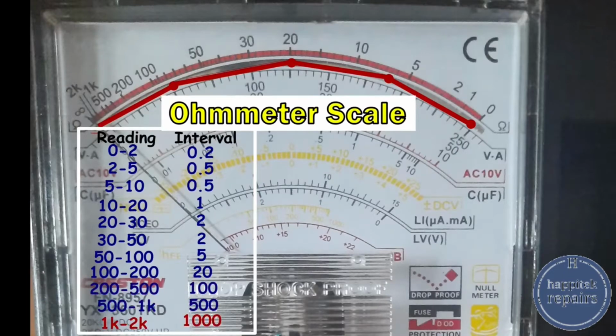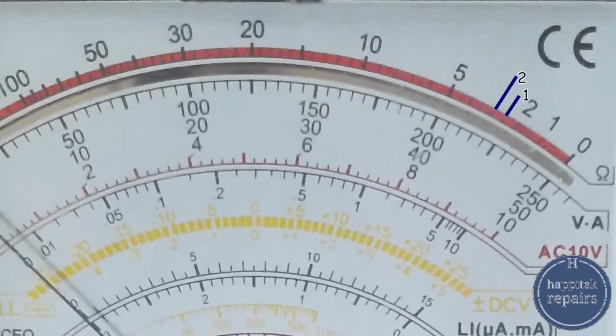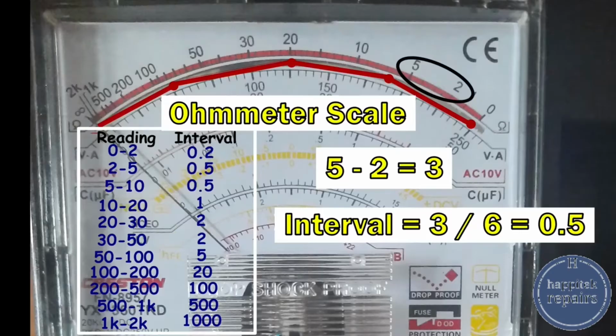If you don't want to memorize this table, read the ohmmeter scale in this manner. For example, in 2 to 5, the difference between 5 and 2 is 3. Let's count the lines from 2 to 5. Here we have 1, 2, 3, 4, 5, 6 lines to get the difference of numbers from 2 to 5.